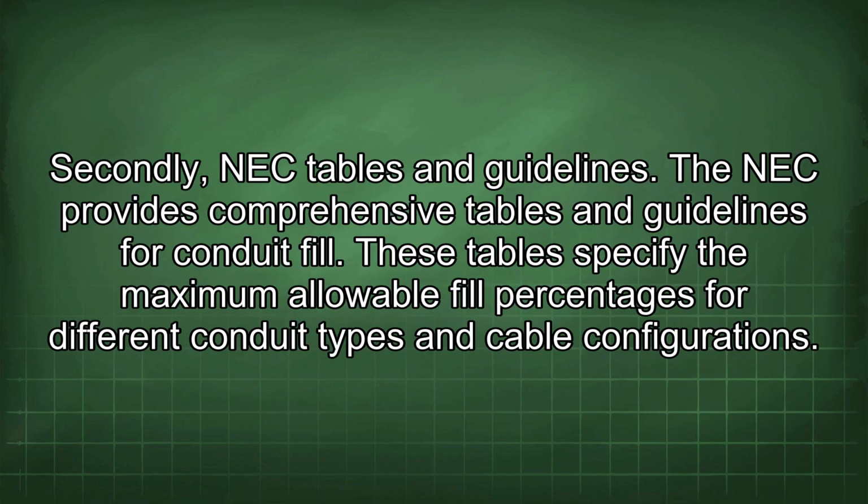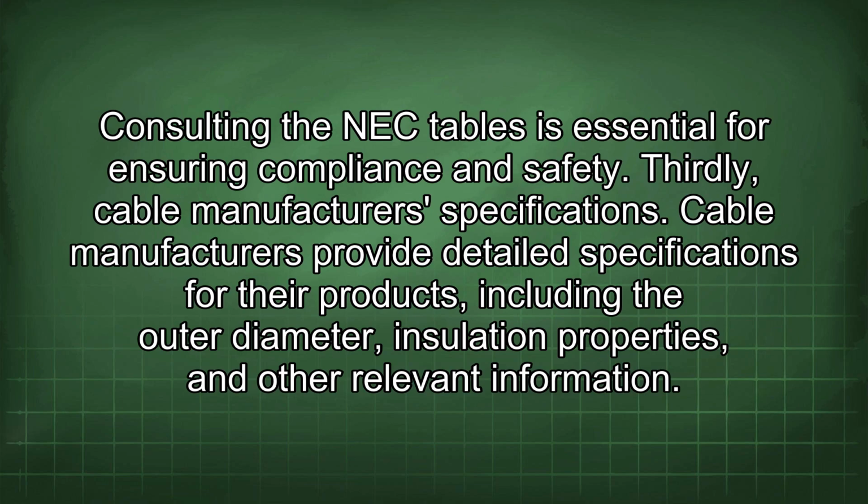Secondly, NEC tables and guidelines. The NEC provides comprehensive tables and guidelines for conduit fill. These tables specify the maximum allowable fill percentages for different conduit types and cable configurations. Consulting the NEC tables is essential for ensuring compliance and safety.